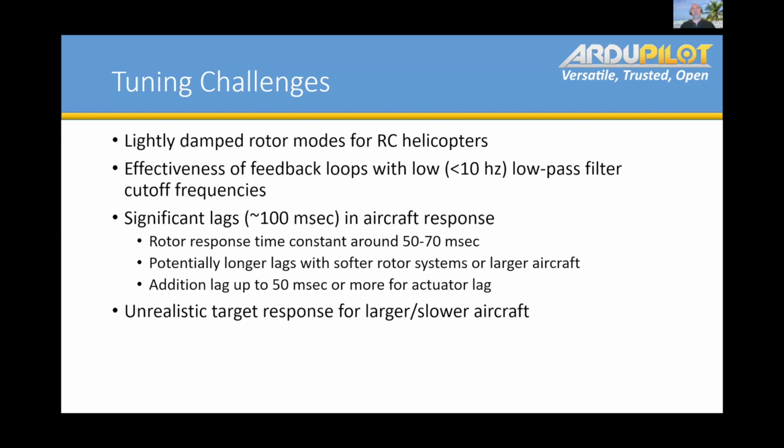Oh, wait a second, Josh, that's right. He doesn't have any actuator lag. He always likes to boast about that. But you do have these actuator lags that you could see. In my helicopters, which are slower, I don't have UAV CAN servos, but I have these traditional digital servos, which are pretty fast. But you still see some lag in the response of the actuator, and that's up to 20 to 50 milliseconds of lag.